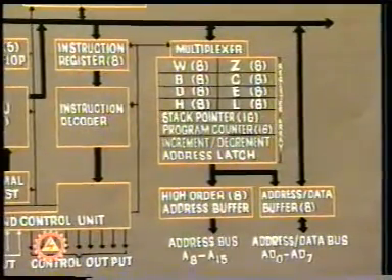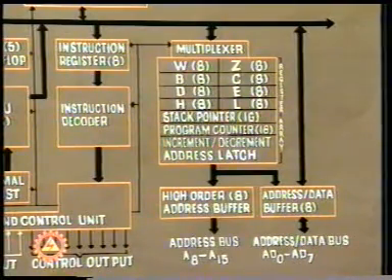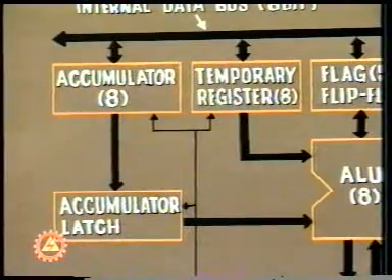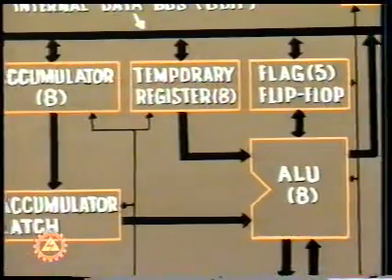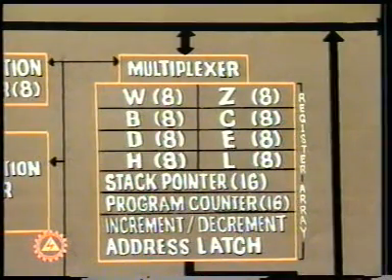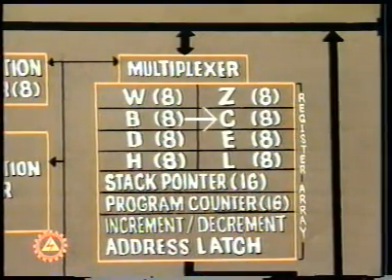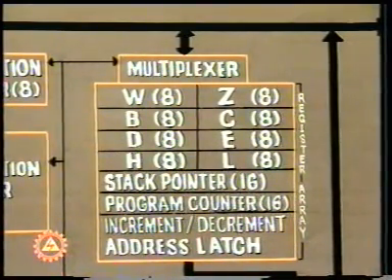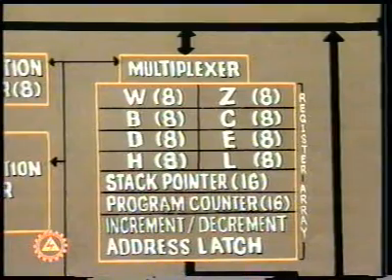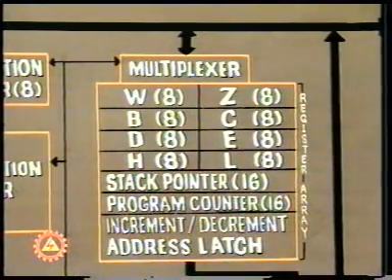It is an 8-bit microprocessor with 16-bit address and 8-bit data bus multiplexed in 16 pins. 8085A has one 8-bit accumulator designated as A register, 6 8-bit general purpose registers designated as B, C, D, E, H, and L. They are arranged in pairs so that they may be addressed either singly for 8-bit operation or in pairs such as BC, DE, or HL for 16-bit operation.